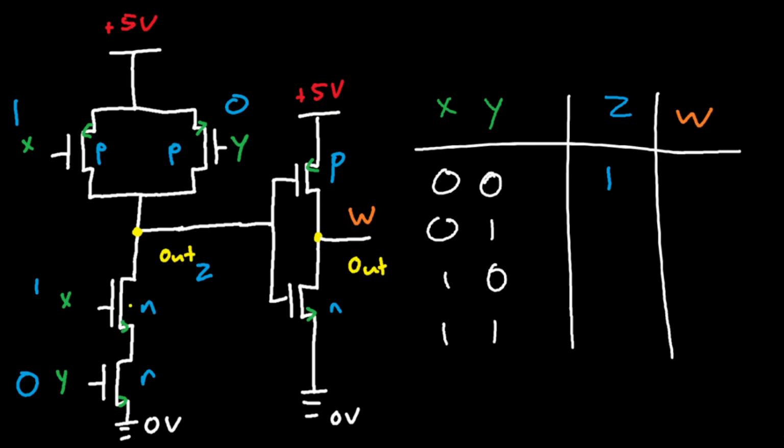I reversed it, sorry: this acts as an open switch, this acts as a closed switch. So this right here allows current to flow through, but this side, no current can flow through. So current hits this output. The output Z is now 1, since this is 1, 0.